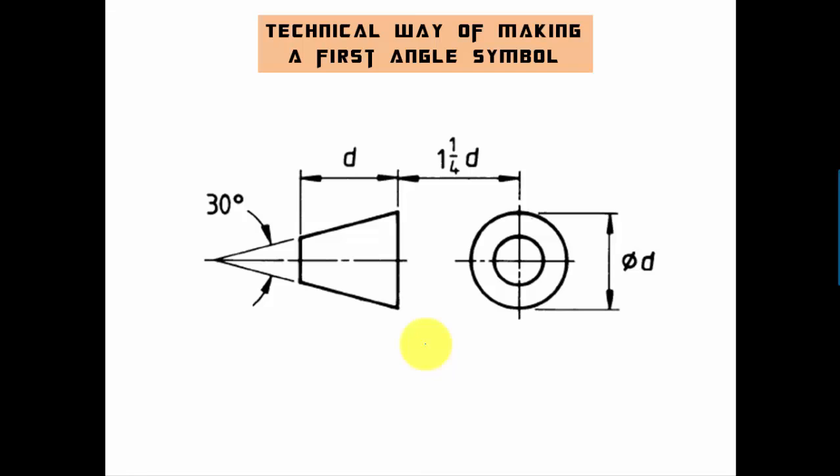Now guys, you can note this down. Phi, let me show you what phi is. Phi is basically a representation for diameter. So when you have to represent a diameter, you put a phi initially, and then you write the value. Let's say we have a circle whose diameter has to be represented, and the diameter is 40, so you write this as 40.